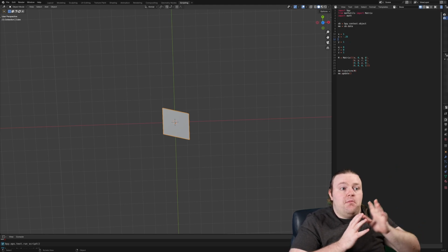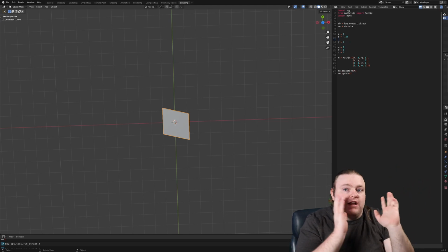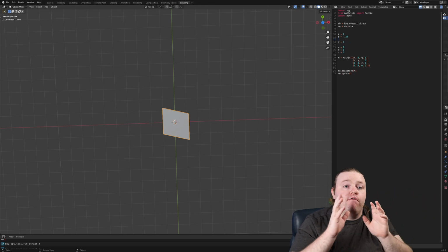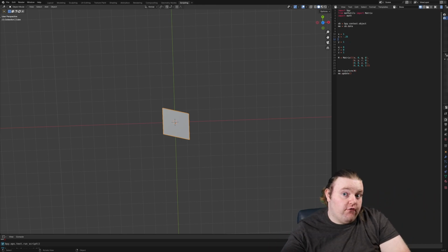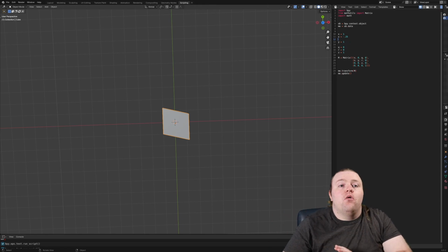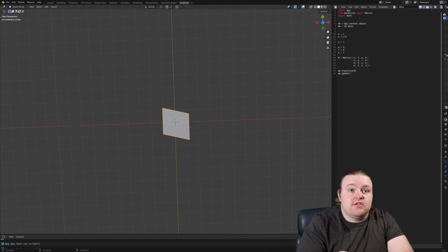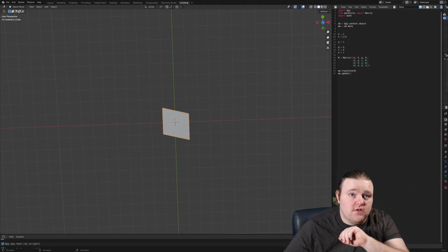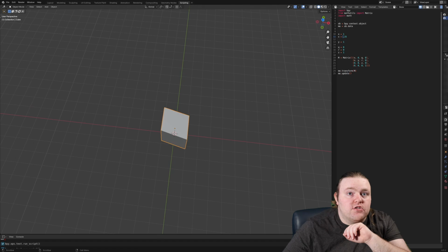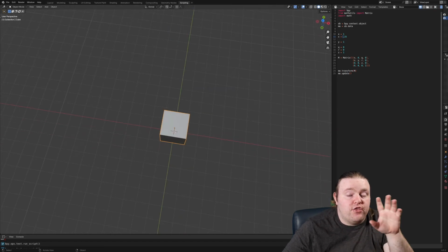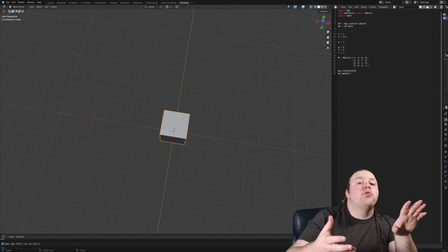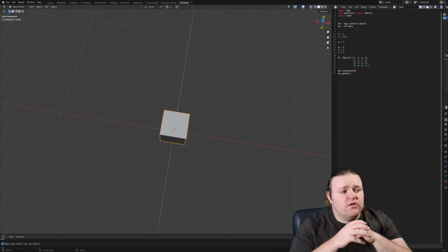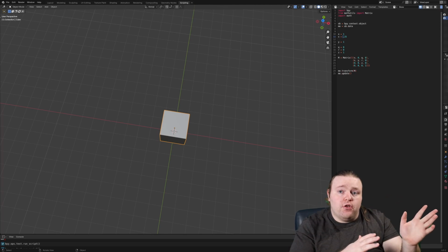We've transformed it backwards. So we started with our cube. That's the model we want. Then we pre-multiply by the inverse of the transformation matrix we'll have to solve for our printer. And then we can run it through the printer. So this looks now with a positive 0.25. That's what our printer is doing to our parts. And then when it runs through the printer, we end up with the thing we wanted because we pre-undid what the printer is doing to our parts. And so we can pre-multiply the inverse.